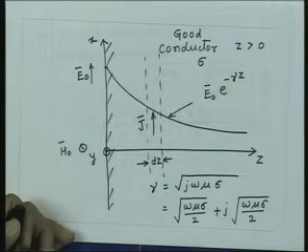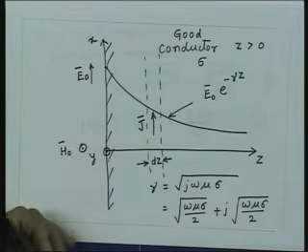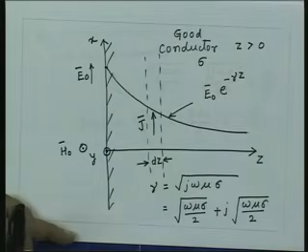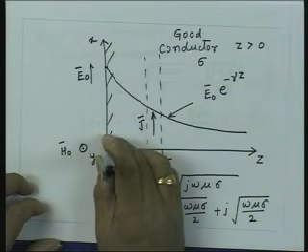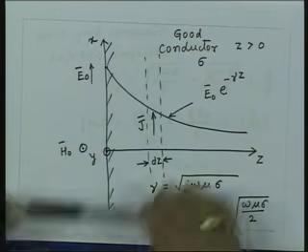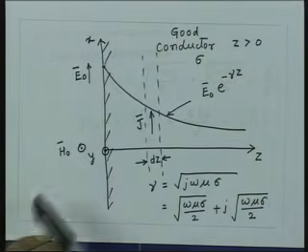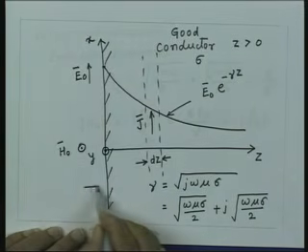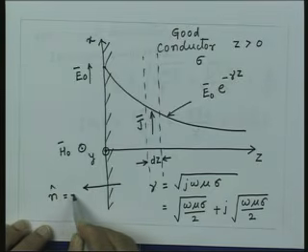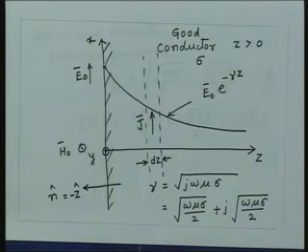So, the direction of surface current also is same as this, which is x direction. So, we have direction of surface current which is x oriented, we have magnetic field which is y oriented, and the unit normal to the conducting surface is this normal. That means the direction of the normal to the conducting surface is n is minus z.